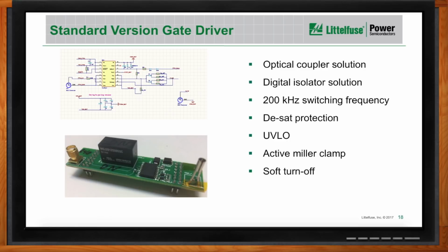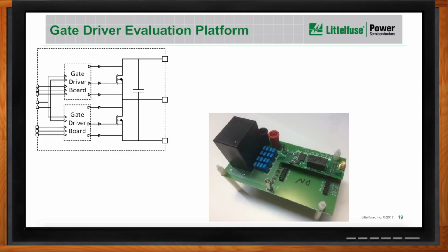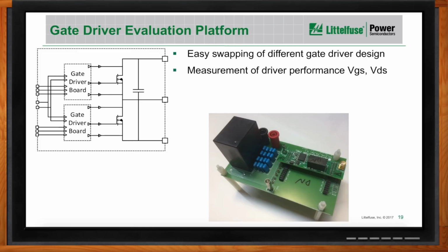So to help our customers evaluate our gate driver easily, we have also designed this gate driver evaluation platform. It's a half-bridge configuration with easy swapping connectors to connect the different gate driver solutions. We also provide different measurement points for driver performance, for example, the VGS signal and the VDS signal of the devices.